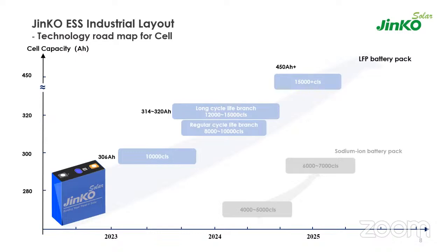But by increasing this depth of discharge to 90%, we'll have the other side of this technology, you can say disadvantages or advantages, where increasing the depth of discharge will definitely reduce the number of life cycles. So it is highly flexible, and it can even go up to 100% depth of discharge. Probably it will touch around 99% or 98%, where the number of cycles can be reduced to 6,000 to 7,000 cycles.